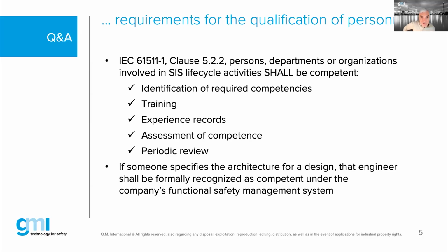61511 today, edition 2 and edition 1, had a specific clause, which is quite complex if you start to read it. The clause is saying that any person, any department, or any organization which is involved in any life cycle activity shall be competent, including the person who is trying to define how many hardware fault tolerance or what is the architecture that you would need for achieving your certain SIL. That means you need to prove the identification of the required competency, most likely written down in the functional safety management of that specific organization or company.